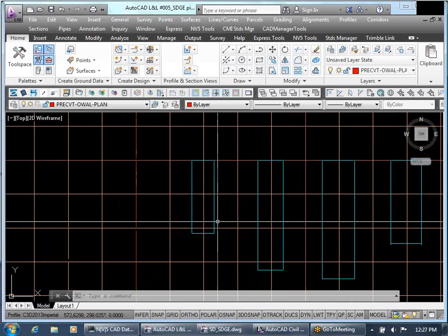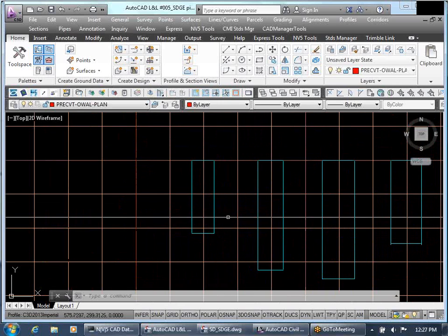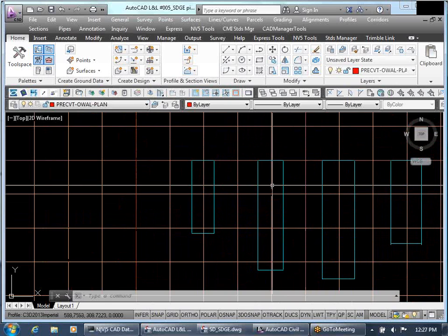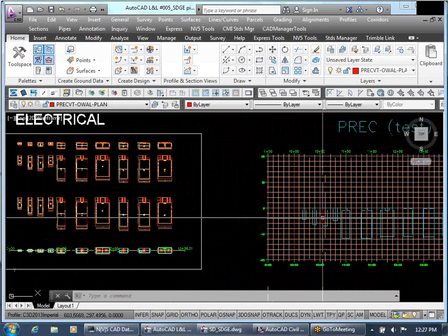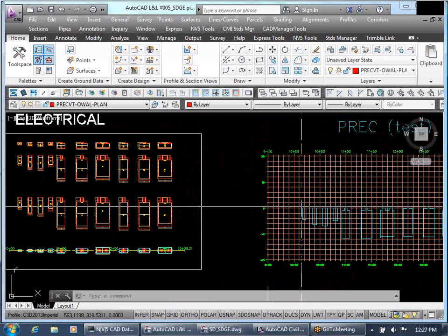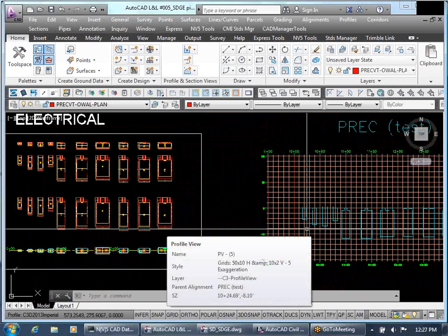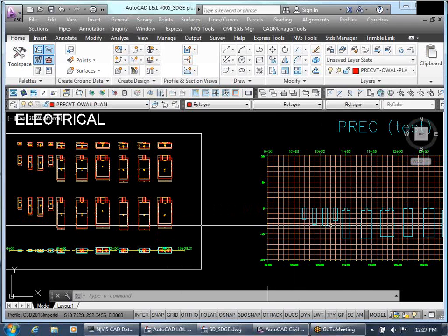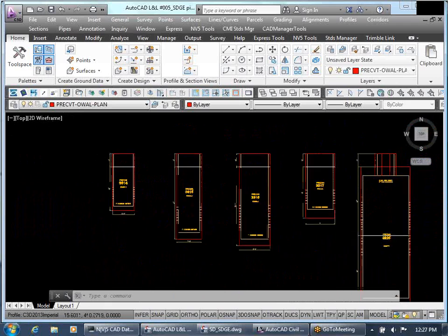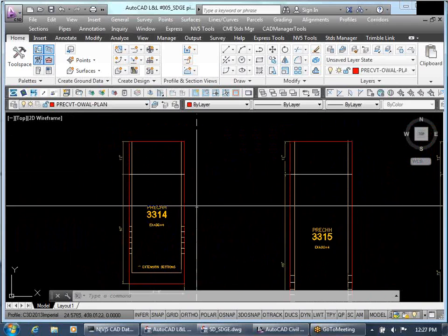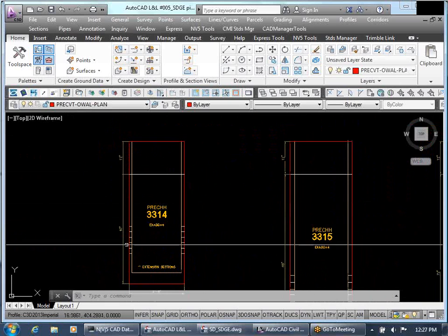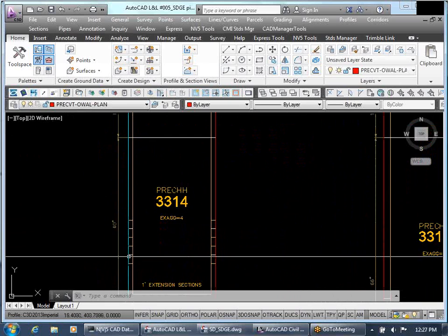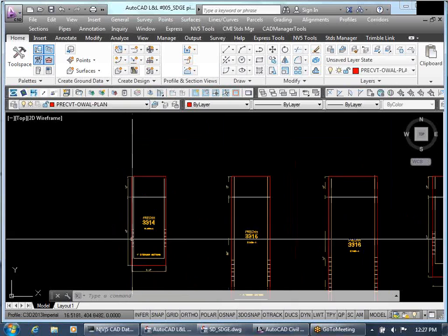However, if you're designing underground electrical, where does your conduit come in? You don't really know using the part, because pipe networks are pretty limited at this stage. We can show the outer boundary of the part, but we can't really add any detail. That's why we have all these profile blocks associated with them. Here you have your knockouts, so you know where your conduit comes in.